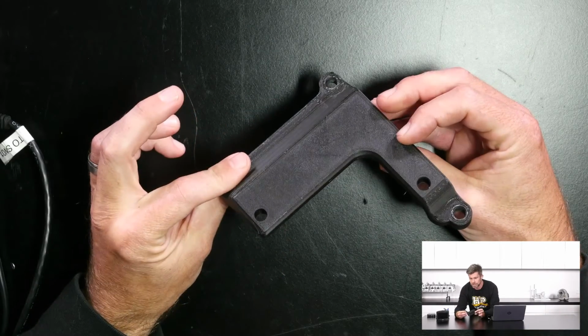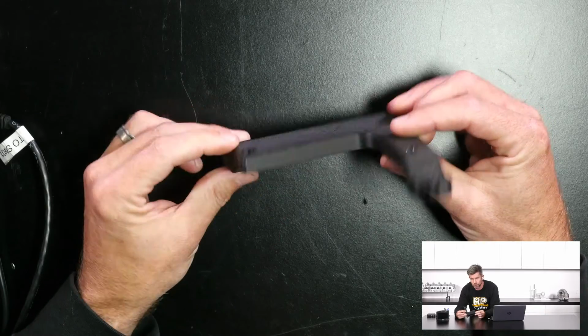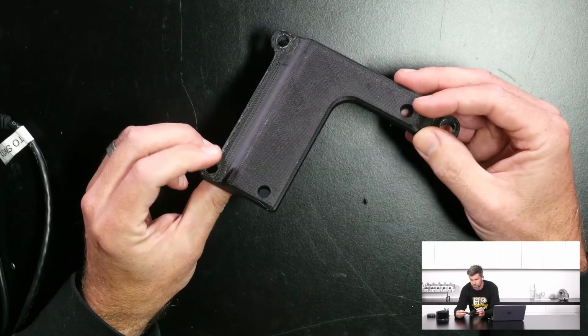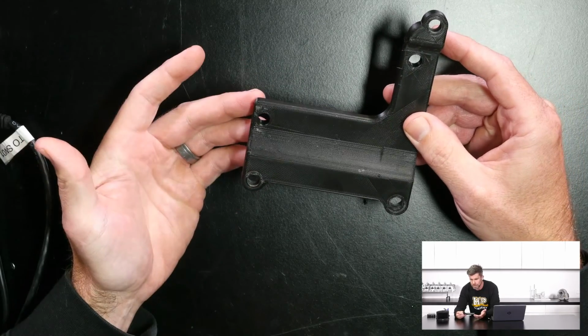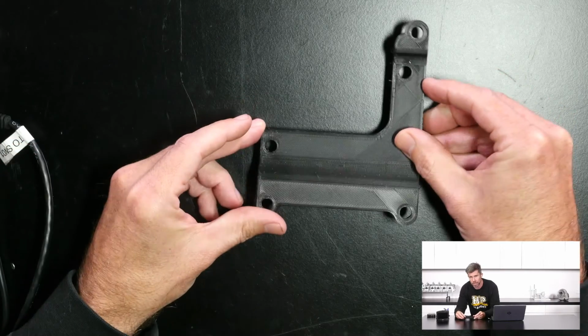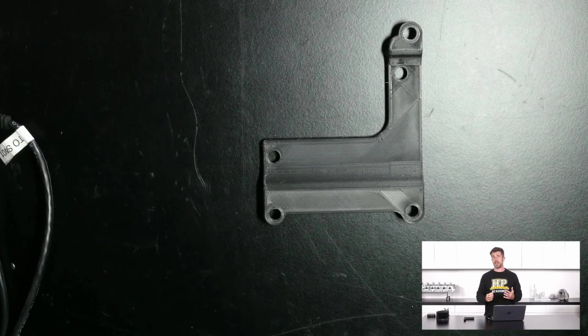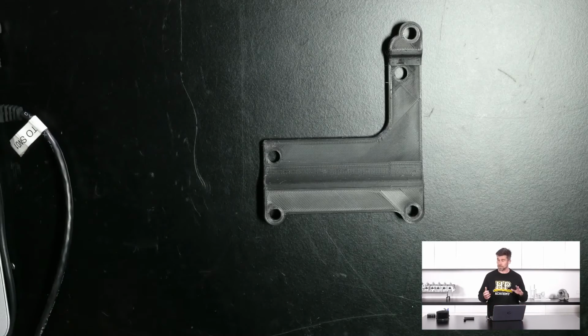So this is printed out of plastic, and before you ask, no, we're not going to leave it in plastic, even though it's actually surprising just how much strength there is in this. But the idea with this is the 3D printer allows us to quickly prototype that and actually prove that it fits. Quite often you're going to find that after you've designed some components in the likes of Fusion 360 or SolidWorks, when you actually go to fit them, there's some sort of unforeseen problem or fitment issue. So it allows you to fiddle around with that model before you actually go to the expense of having that component actually made on a CNC mill.